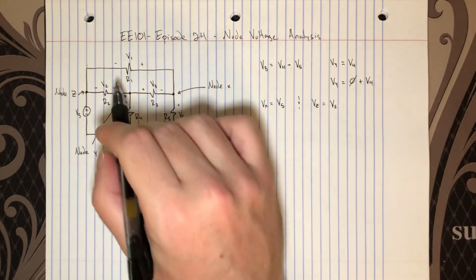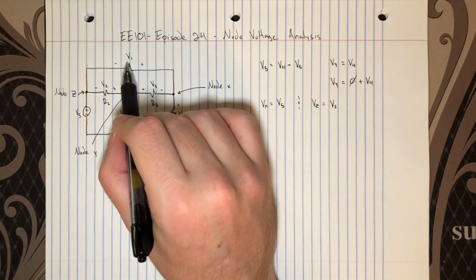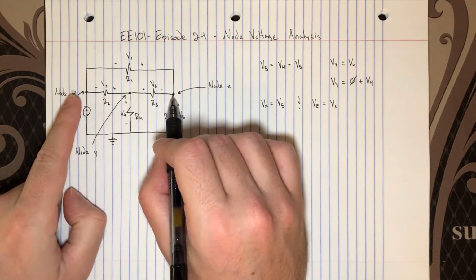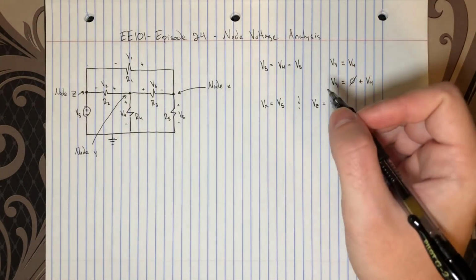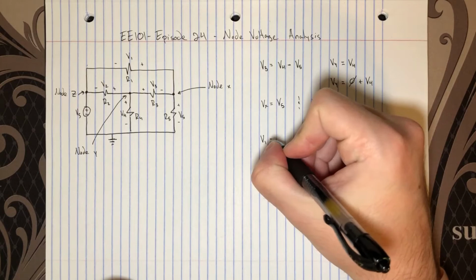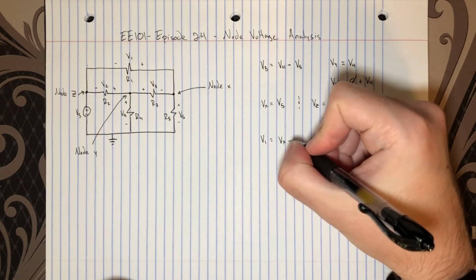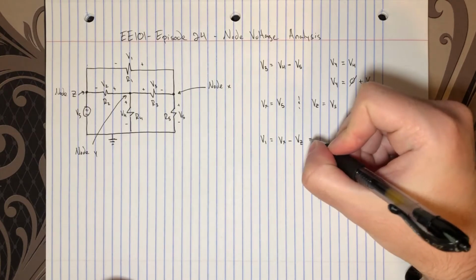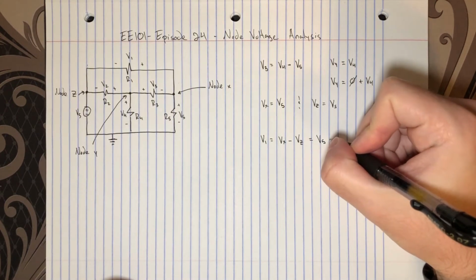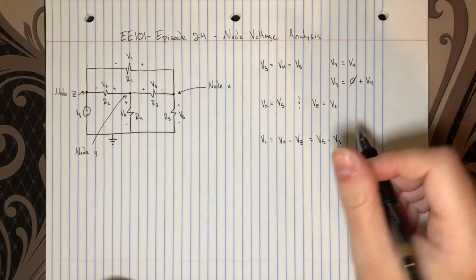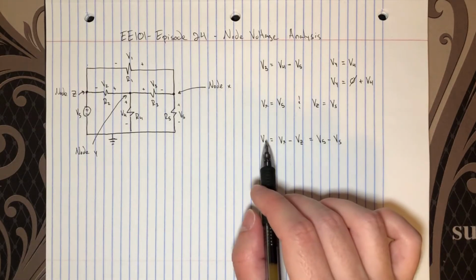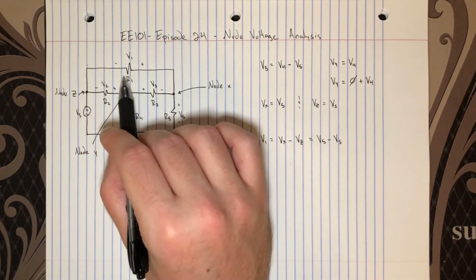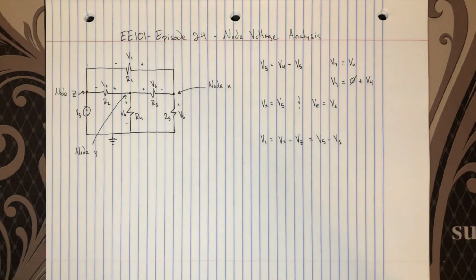So then I can very quickly find the voltage V1 by taking the difference between the node voltages that surround it. So let's follow the polarity that I have drawn. Then V1 would equal Vx minus Vz, which equals V5 minus Vs. And these are allegedly known voltages in the circuit, V5 and Vs. And then given that we know V1, and you have a resistance there, some circuit element there, then you supposedly can solve for the current and power and so on.